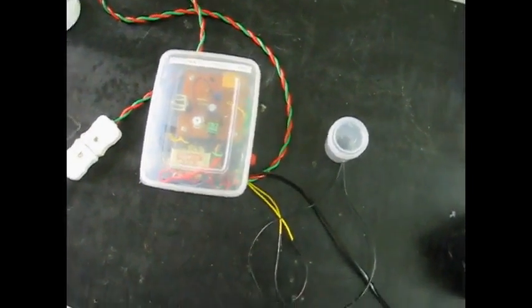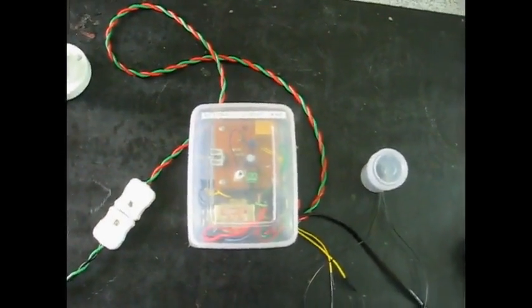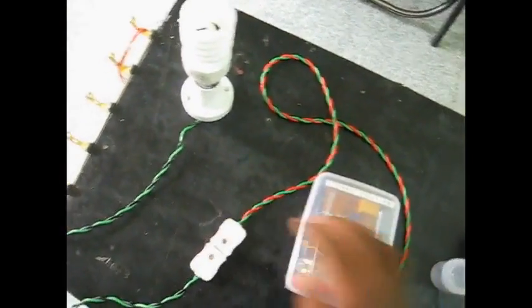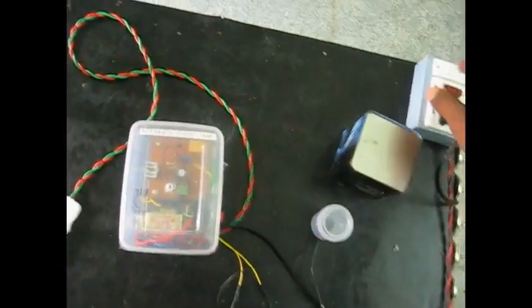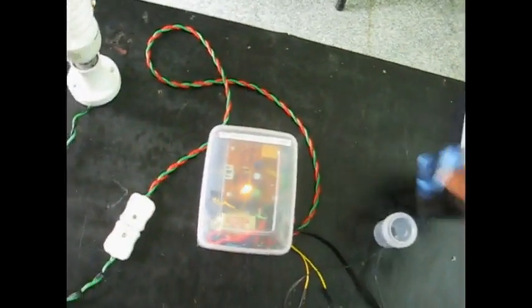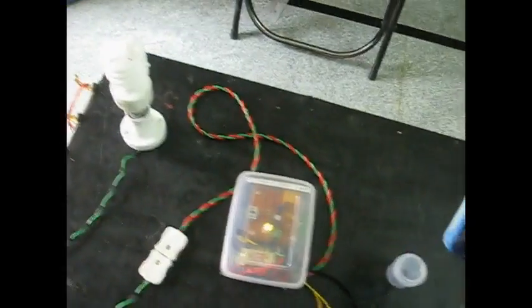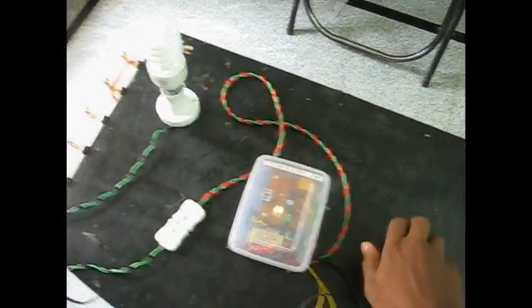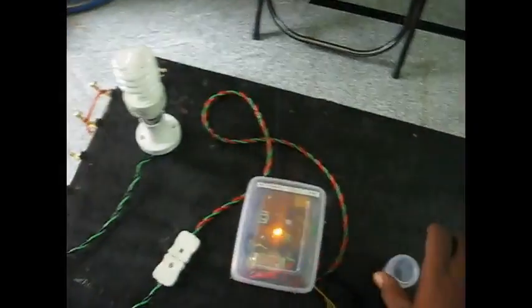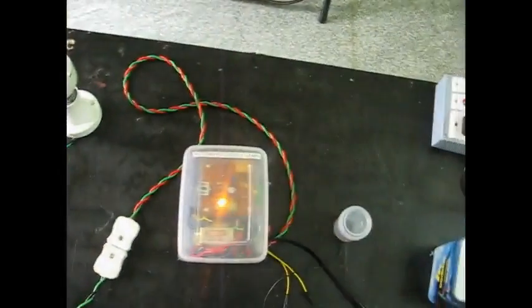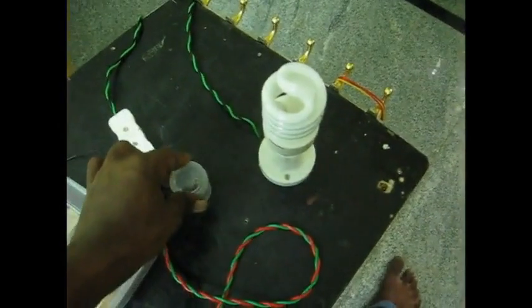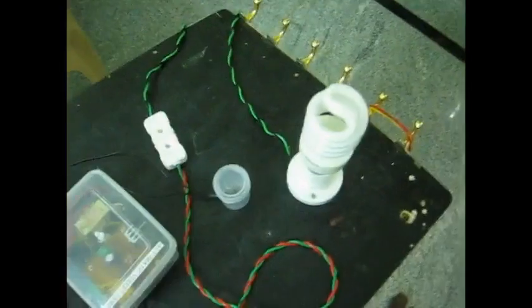Successfully completed the project. Now it's time to check the final working of the device. So I connected the input to the mains and the output to a power saving lamp, and here is my LDR. Powering the mains. The device works well. One thing you have to note down here is not to place the LDR closer to the bulb. Let me explain why.